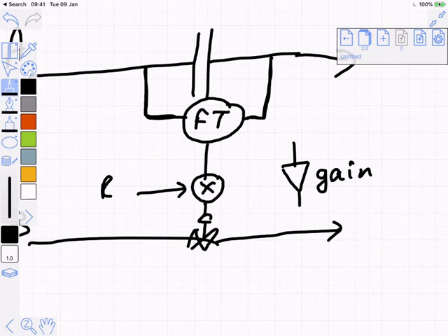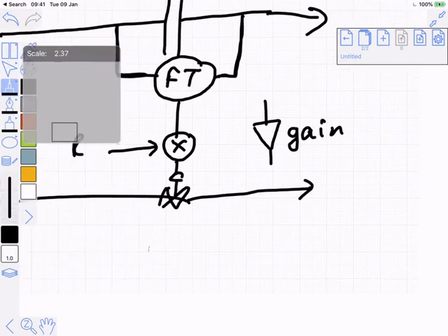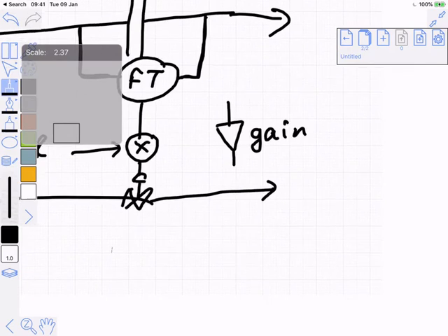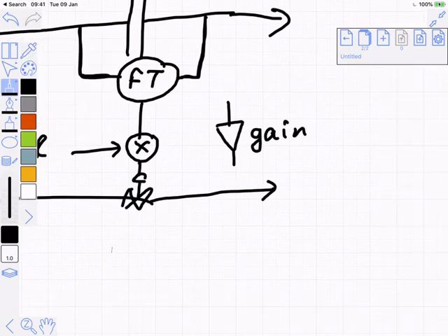Right? And so the difficulty comes from actually picturing the actual way that this stuff will work, because if that is a real orifice plate, and if that transmitter is actually measuring a pressure difference, then we have to remember that in broad strokes, most of the time, flow is actually proportional to the square root of the pressure drop.